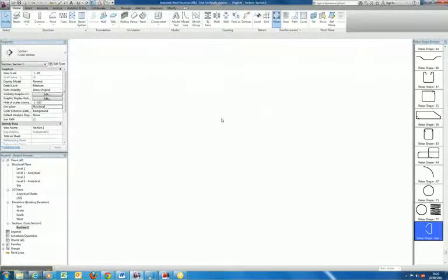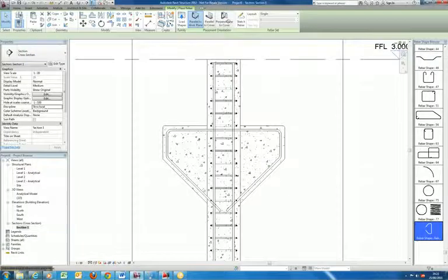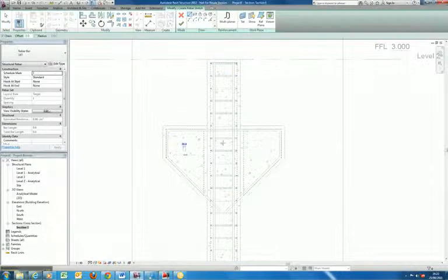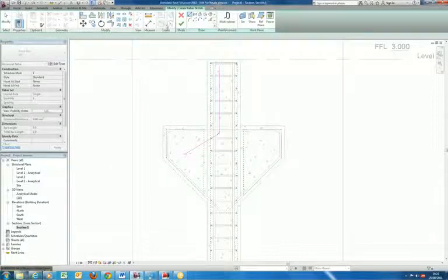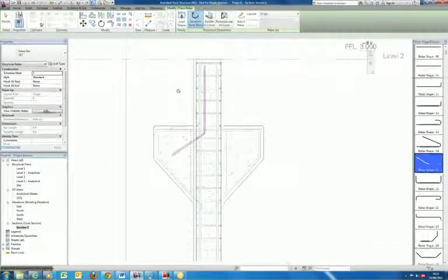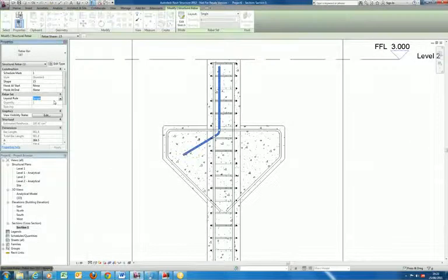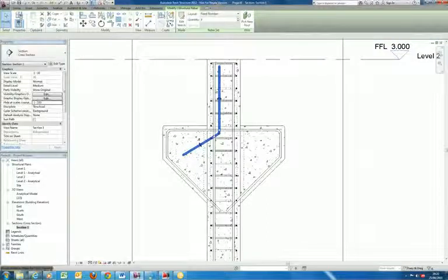Add a bit of rebar. We're going to sketch it. From this point, we'll take it across again, T16s. Finish it out. We'll add 3 of them in, same as last time. So we'll say it's a fixed number of 3, and again we're going to mirror on the axis.